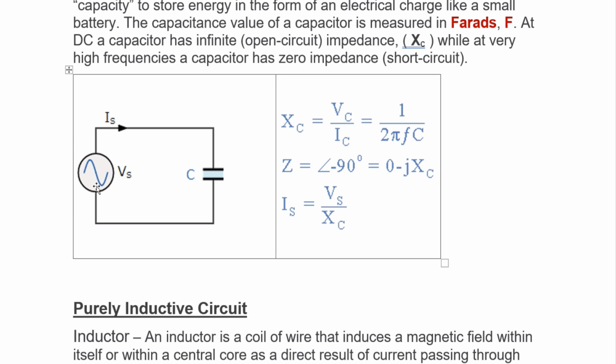So that is it. So why it is said that it behaves like an open circuit in the case of DC? Having applied a DC voltage here, this capacitor will charge up to the source voltage, and then having charged as the positive plate in terms of positive voltage and negative plate in terms of negative voltage, the polarity appears across this capacitor and it stands as a battery itself against the battery it is having here. So the current stops to flow. No current will flow through this circuit in the case of DC, and it behaves like an open circuit.